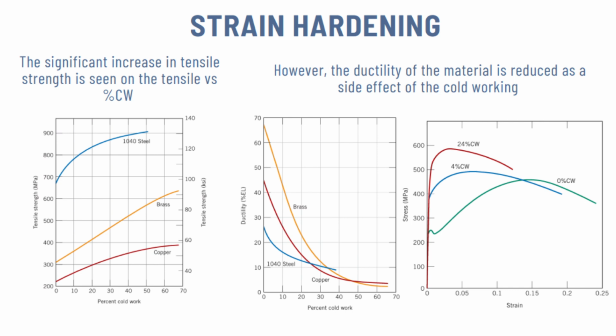However, when comparing the strain of the carbon steel which has 0% cold work on it with the 24% cold work, it can be seen that the side effect of strain hardening can make the material fracture much faster, therefore making it less ductile.